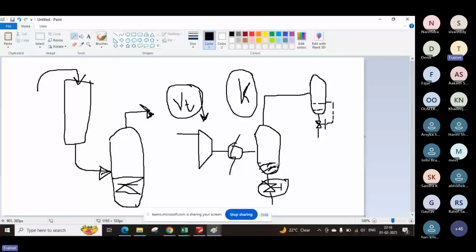So if it is this kind of intermittent application or very low liquid content in the gas, then you don't have to go for a control arrangement. But if your system is continuously operating and you need monitoring of the vessel, then obviously you have to provide alarms, trips, then pressure gauge requirements, safety valves, and all other requirements.